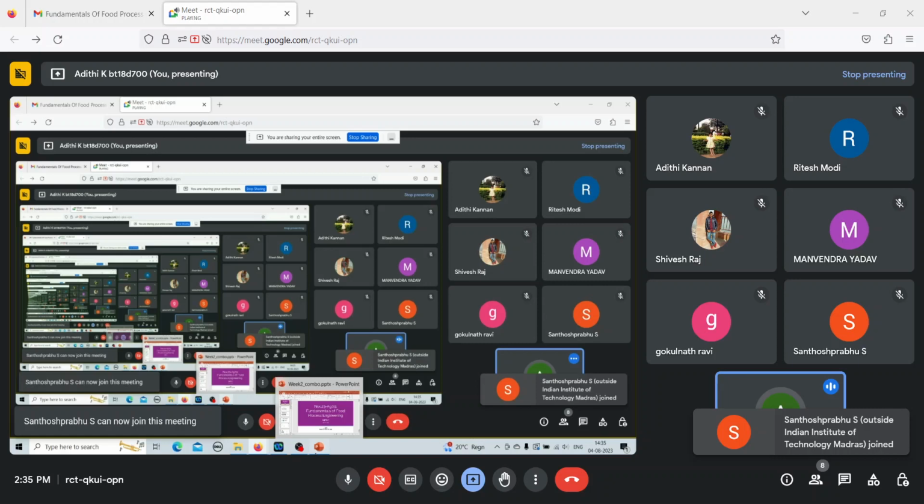In a falling sphere viscometer, you will have a vertical glass tube that is stationary, filled with a fluid, and a sphere of known size and density is allowed to descend through the liquid. That is, the top part of the cylinder will be open, you will put a ball through it, and the ball will now descend through the liquid. If correctly selected, it reaches a terminal velocity which can be measured by the time it takes to pass 2 marks on the tube.